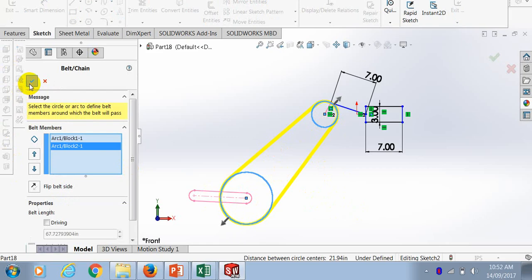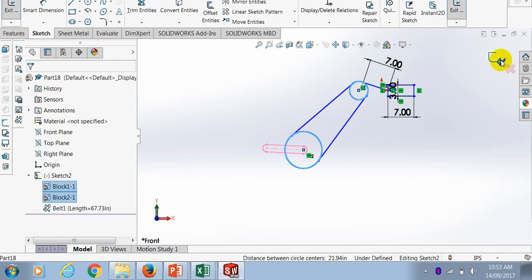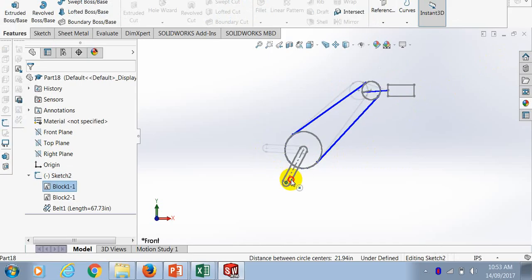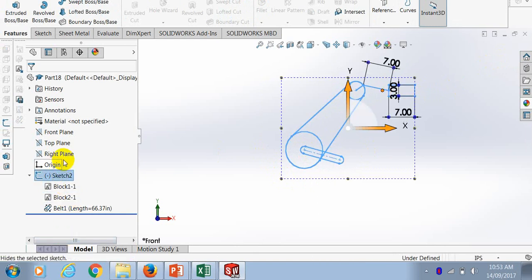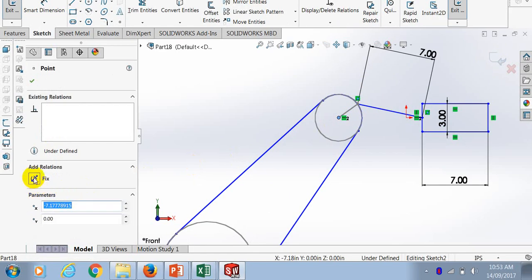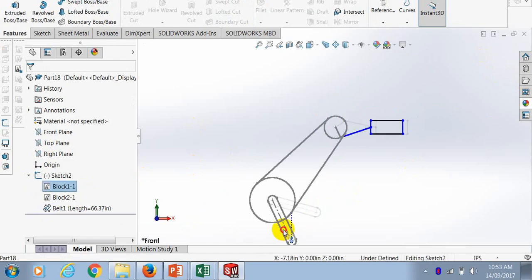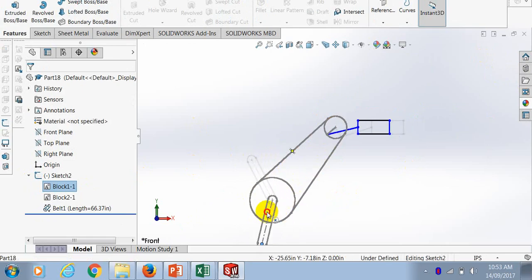Kind of interesting. If I press that, now the relation has become a little more interesting. So let me just get out of the sketch, removing all the dimensions. And now look at that. Now if I move this, this whole thing moves, except that I should fix this center, because when you go to a sketch again, edit the sketch, I can simply press this button and fix. And now look at that. So now we have that interesting mechanism here. Obviously, because this is twice as large as this, every time you rotate one full turn, the other one goes 2.